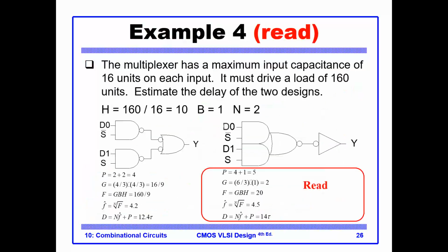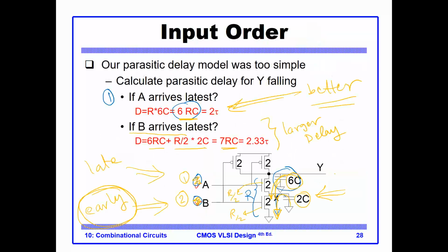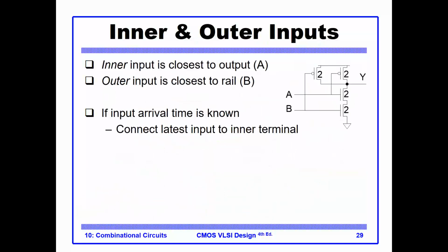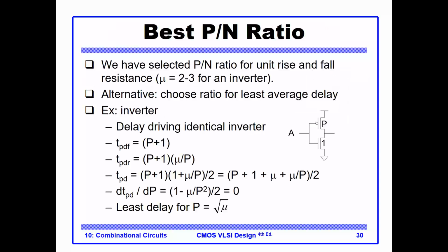Okay, so this is basically what we stated. Then what we have here in this is that we are asking ourselves the question, what would be the ideal size of a PMOS? So far in the course, we're using 2, the W over L for the PMOS equals 2. Now, 2 is ideal for fall and rise time. But is it ideal as well for the delay?